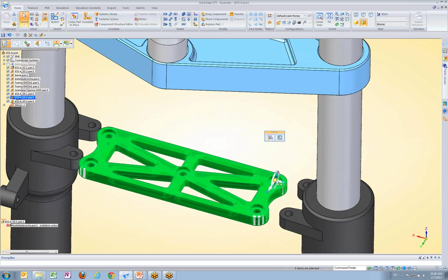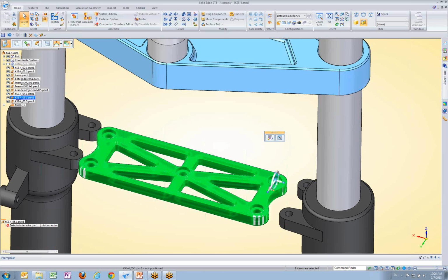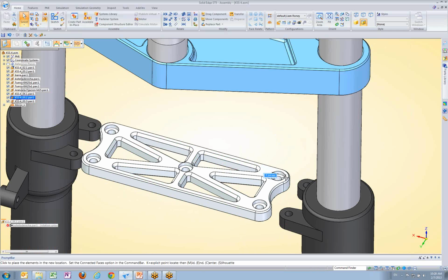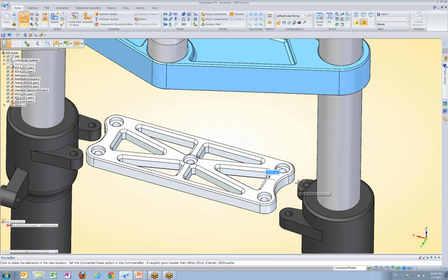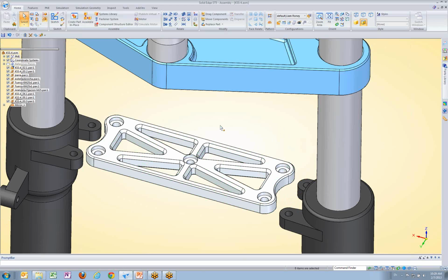So having my steering wheel on here, and again I'm moving the whole part because I'm in part priority. I'm going to click on a move and just walk that back and just pick up on a key point here. So at least I know now the bracket is in line with these holes, even if it's not the right span. So using the steering wheel, it's kind of like another assembly relationship. We can physically move things into the right place.